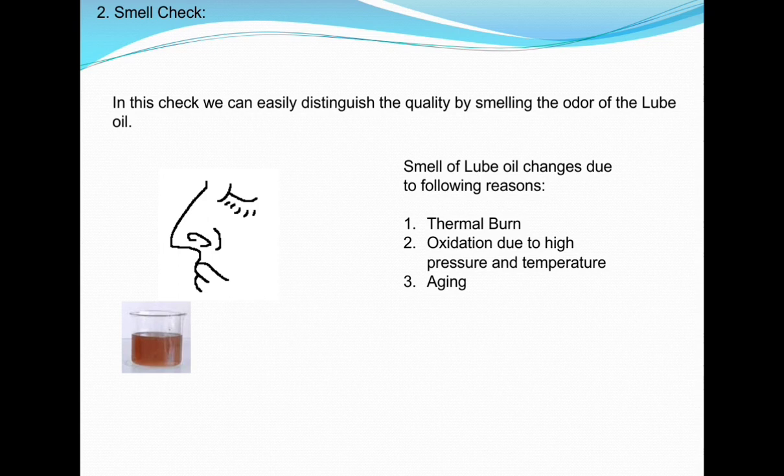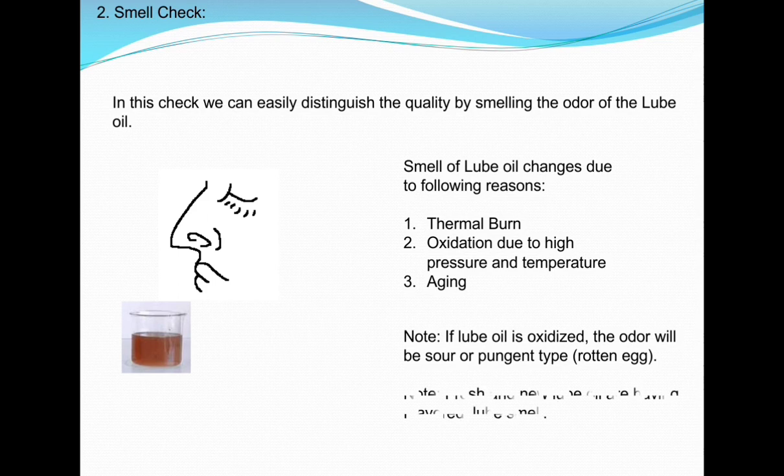The changes in odor can be due to the aging factor, due to the thermal burn subjected to high temperature for a longer period, due to oxidation. So this smell check also is a determining factor to know what all about the oil analysis.